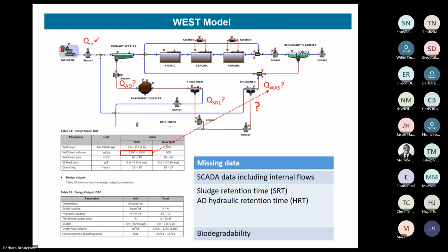We did refer to the design data to try and infer some of these missing measurements, but the other plant problem Kwamashu is having is a problem with their solids removal contract. So they were running it at longer sludge ages than design. So even the design data wasn't necessarily reflective of what's going on.